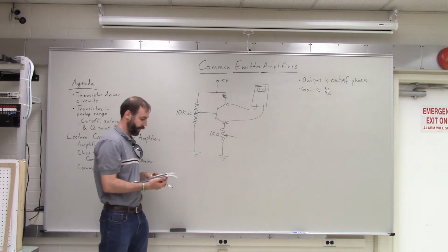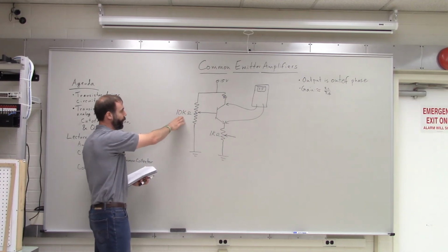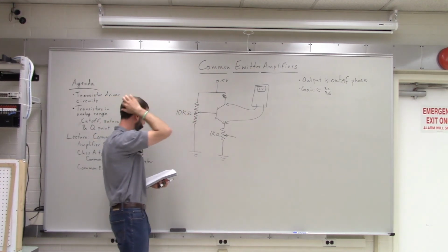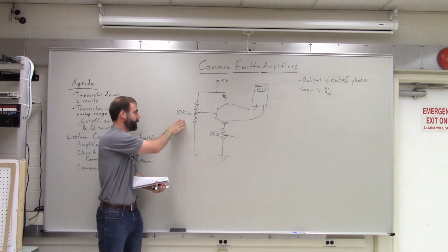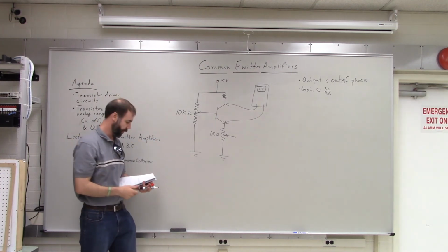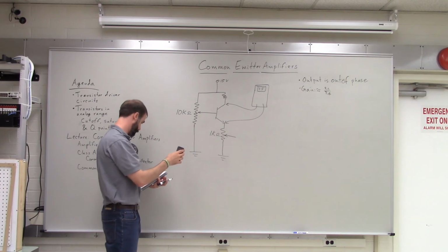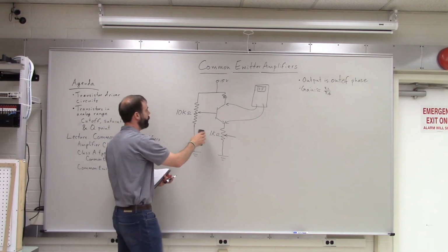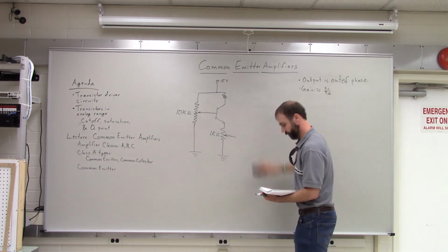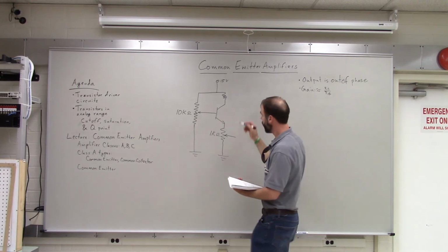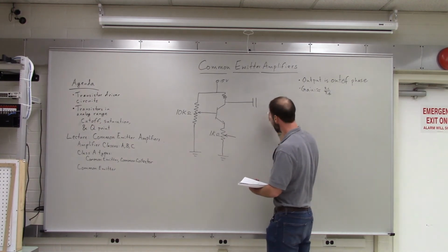For the second part of this circuit, you're going to add on to what you've done in the first part. So once you set the quiescent point for this potentiometer, you won't touch that for the rest of the lab. All right, you're going to leave that because that's got your amplifier set up. So after this, you're going to take the meter away, and you're going to add on to this circuit. So you're going to add on to the output. You're going to have a capacitor there.